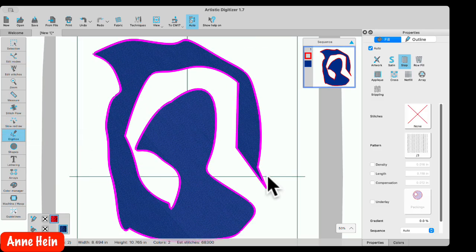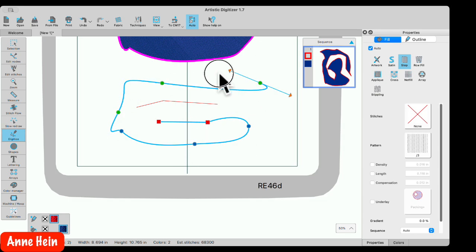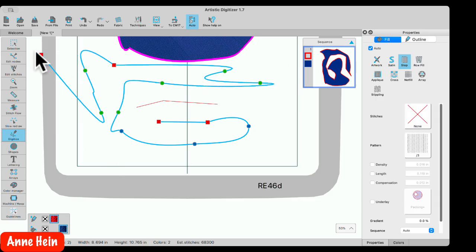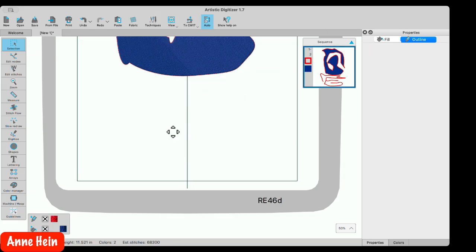Also, when you're playing with this one, let me go back up. Left clicking, you're getting your straight nodes, and then if you shift and click, you get curves. If you're dragging, you'll have your Bezier in there. So some people like that all the time. So you can do it that way. If you're in your tool and you're like, oh, I want to stop, hit the Escape and it'll end that for you. Then you can select it and delete it.